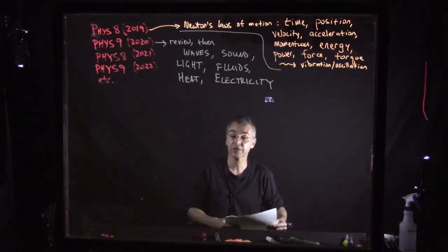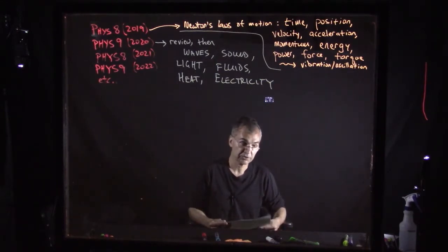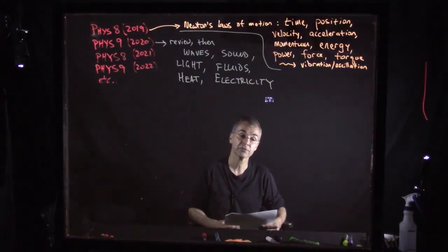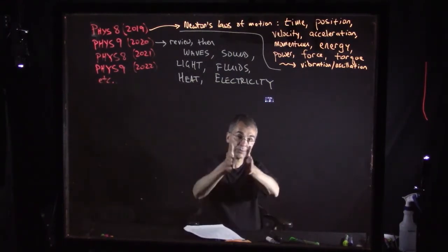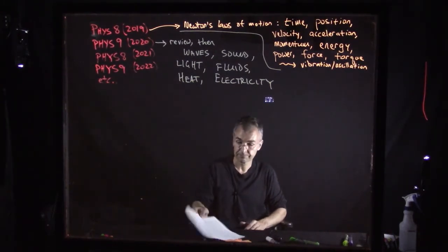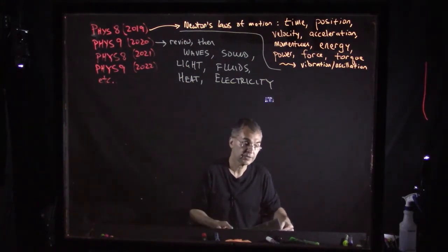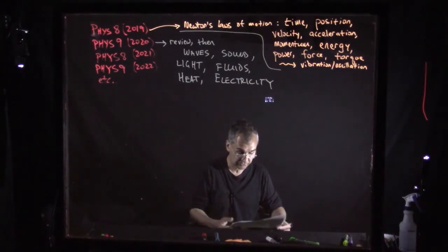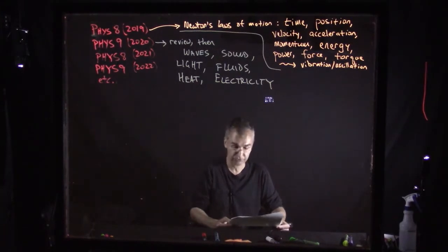It also often turns out that some of the things that you have to do to make a building more energy efficient have the side effect of improving its acoustical comfort. It's interesting that these things connect to each other, in that thicker windows or double layer windows or better insulated walls often improve the acoustical separation between spaces. Sometimes with more energy efficient air conditioning or heating systems, the motors run at a lower power and they're inherently quieter. So sometimes it turns out that environmental comfort has a nice side effect of acoustical comfort.